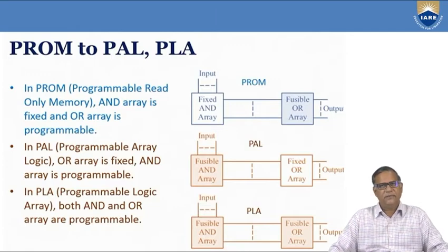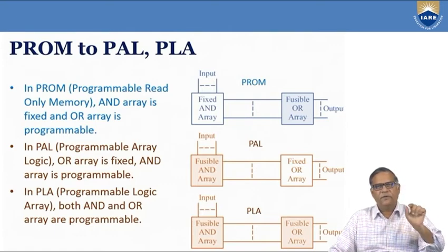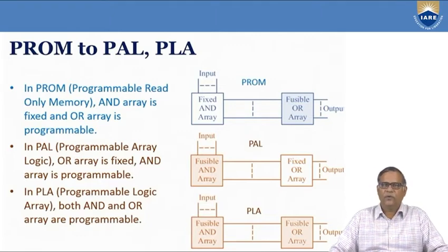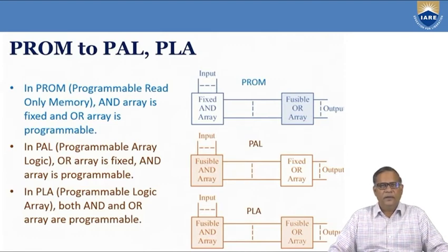But suppose you want to use the same IC for different applications or different programs, you have to introduce the element of programmability. If you introduce the programmability feature, you can use the same array of NAND gates, NOR gates present inside the IC to function as encoder or decoder or multiplexer or demultiplexer. So the programmability enhances the flexibility and you can use the same IC depending upon the requirement.